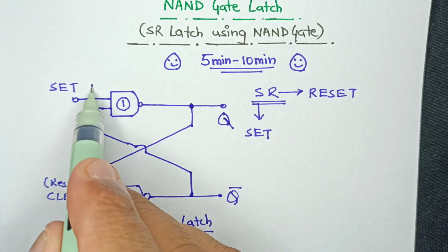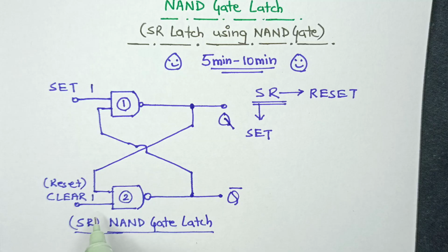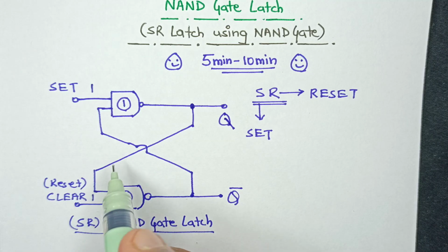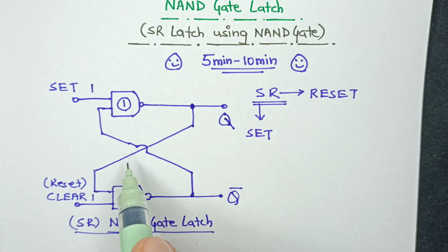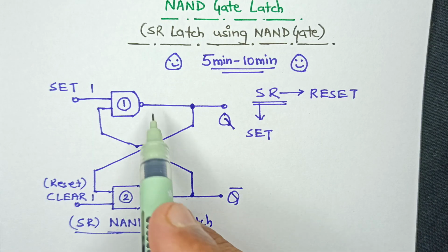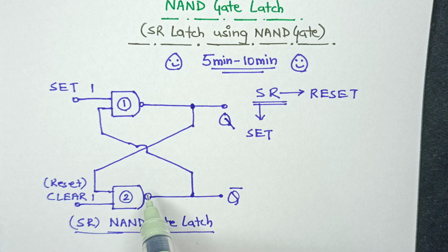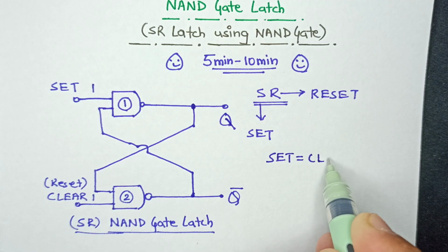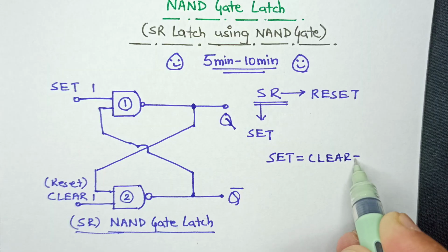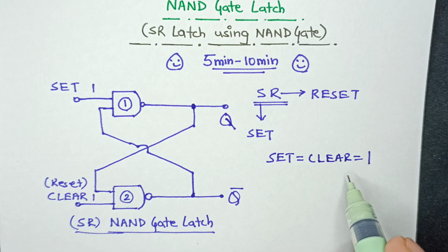So which means that this output would be 1 and even this output would be 1 over here. Now whenever we want to change the latch outputs, one of the two inputs will be pulsed as low. So either it can be this one or this one. Now let us begin our study by showing that there are two equally likely output states when the first one, let us say, is set and clear.